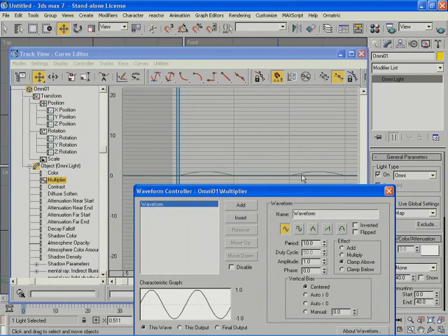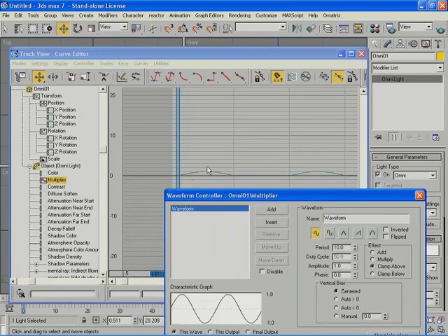The second thing I want to change, if I have a waveform here that goes like this, is a sinusoidal waveform. In case I have a sinusoidal waveform, it's going to increase in intensity, reach a peak, and then go down. So the intensity is not going to stay static. With the stroboscope, you always have a static intensity. So it emits light, but always at the same intensity. Therefore, I should not be using a sinusoidal waveform. Instead, I would use a linear or square waveform, and that way it's going to keep the same intensity and then 0 and then regain that intensity.